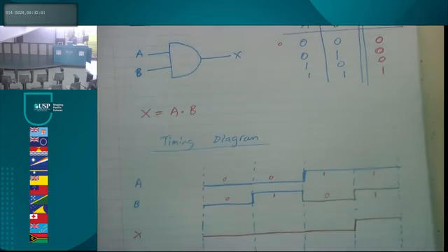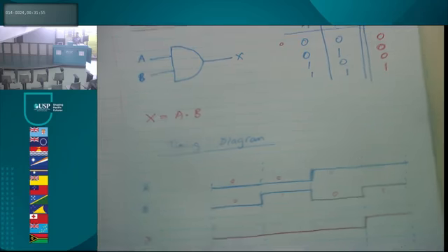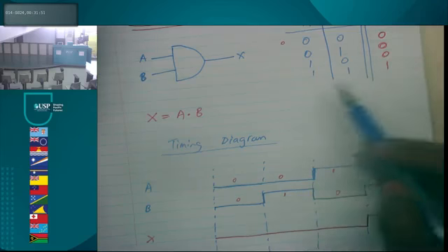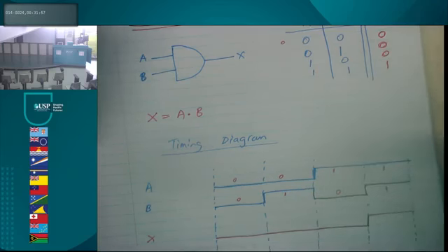So you guys have understood AND gate for now, right? Is it okay? So basically, you can see for AND gates, what can you see? Do you see that for your 2 inputs, whenever it's high, that's the only time your output will be high? Did you notice that? Right? So basically, he was saying that you cannot use multiplication, but earlier, we did use multiplication, right? So 1 times 1, that's the only time you'll get 1, right? Other times when it's 0, with a multiplication, you'll always get 0. You understand that, right? So it's a simple Boolean expression.